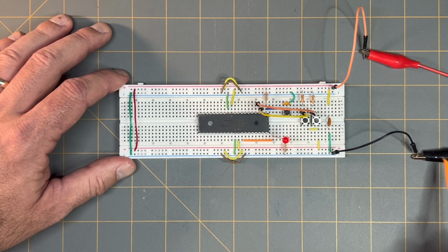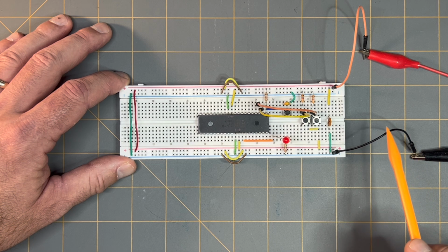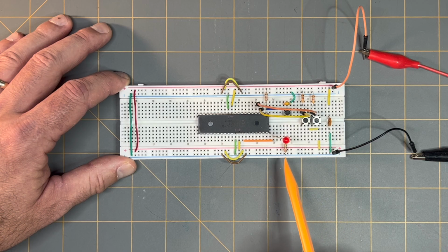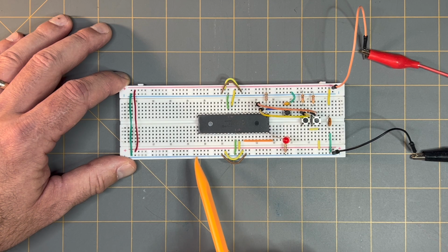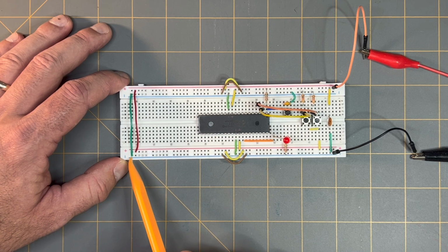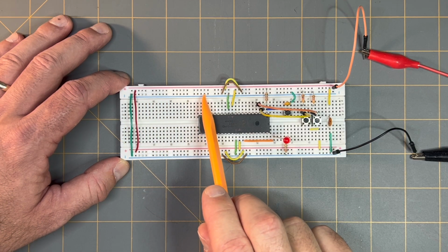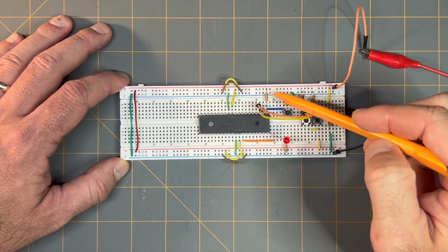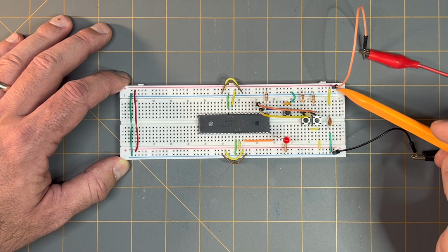And similarly, we have our negative supply here from the power supply, and it's connected to this black jumper wire, and that negative supply is continued through the negative power rail on this side of the breadboard through this brown jumper wire to this end of the negative power rail, across this green jumper wire, and then continued down from this side of this negative power rail through this brown jumper wire, and continues down this end of the negative power rail to the end of the breadboard here.